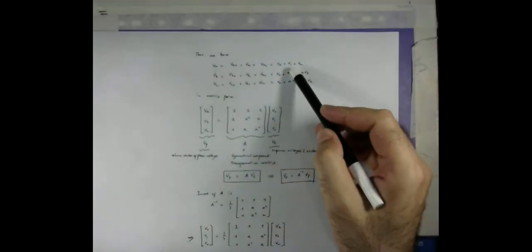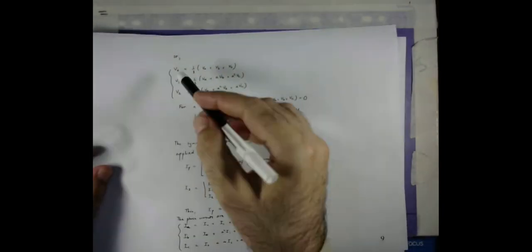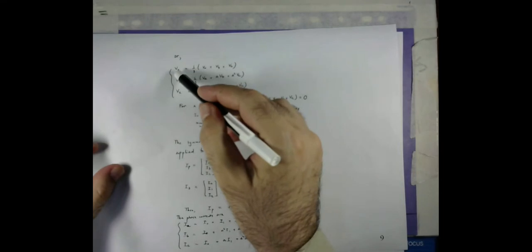IB, which is the phase B current, equals the zero sequence component, plus the square of the operator A times the positive sequence, plus the operator A times the negative sequence. Similar is the case for the phase C current. So let me now also, in the same manner as what we wrote here, write zero sequence voltage equal to 1 over 3 times phase A voltage plus phase B voltage plus phase C voltage, or phasor A plus phasor B plus phasor C.